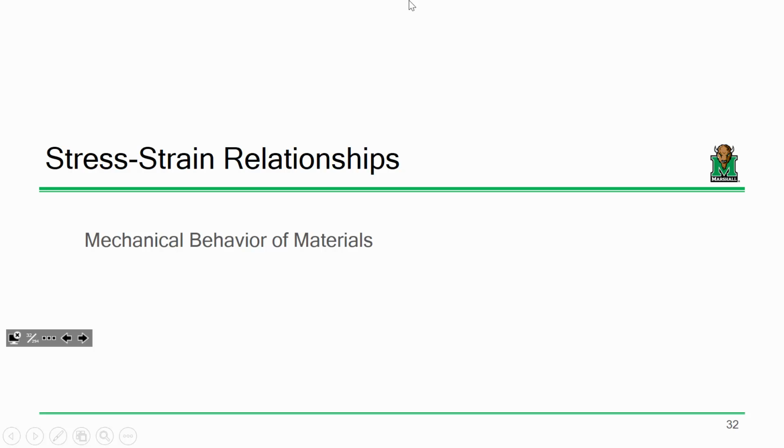Well, just for the purposes of discussion, let's say I'm looking at something like this eraser. An easy way of calculating, let's say, the volume of this eraser would be the area times the length. Is that a fair point? Area times the length, assuming I can stay a hold of it. All right? We've taken the area out of the equation by defining this concept called stress. Well, we don't care so much about the load, we care about the load per unit area, and that's where this whole stress concept comes into play, right? So we take the area out of the equation.